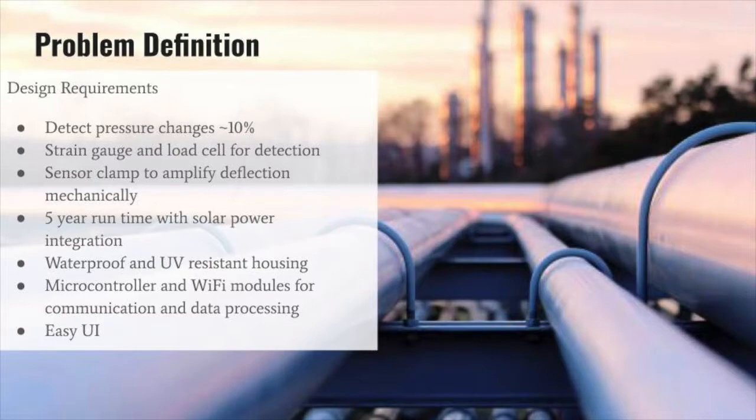The housing of this sensor will be waterproof and UV resistant, using gaskets of 3 millimeters to create a seal between the top and the bottom, and finally, coating the housing to ensure it is both water and UV resistant. The housing itself will also be designed to accommodate for serviceable items such as the battery.